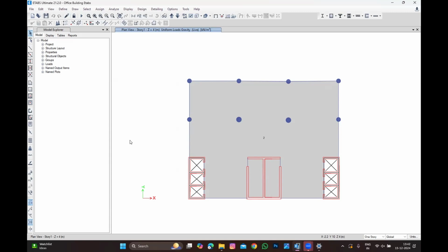If you don't want, I will give you the calculation for the cladding. What is the glass thickness you're using for glazing? 8 plus 6. Okay, so 8 plus 6 will be 14 millimeters, right? What is the density of glass? 25, which is equal to concrete density, right? Do it: 0.014 multiplied by 25.